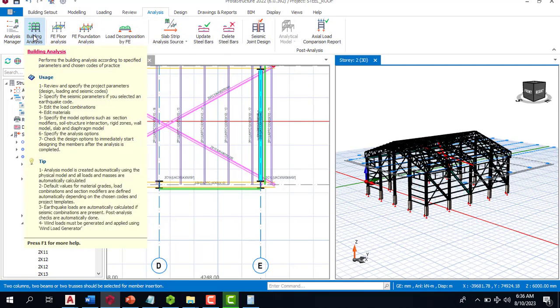Okay, so all you need to do is just to run the analysis, know the right steel cross sections, because by the time it analyzes it for you, you can just play around with your utilization ratio, your slenderness ratio, in order to strike a balance between them. Once you are able to strike a balance, that will definitely be the most economical and safe. So the software is there to guide you to adopt the most economical steel cross section.